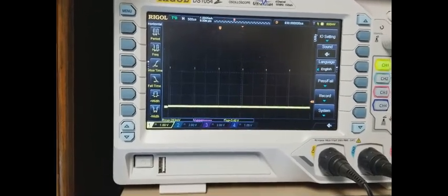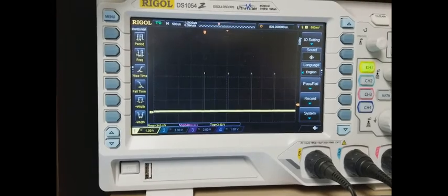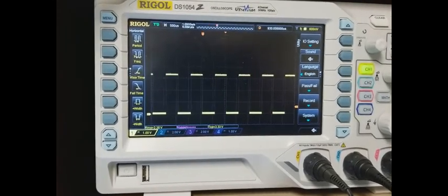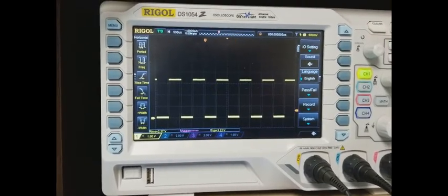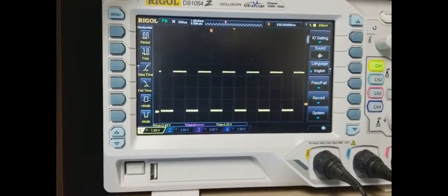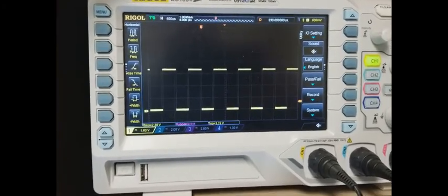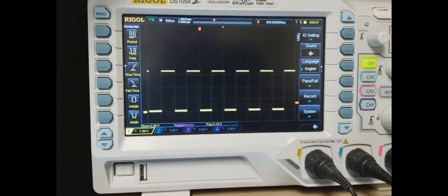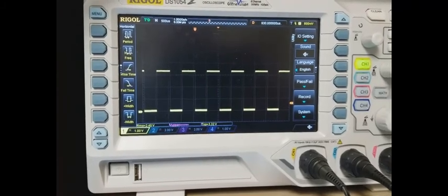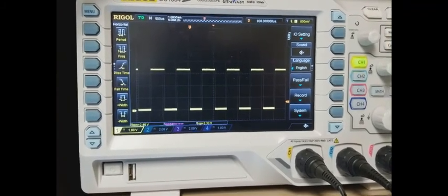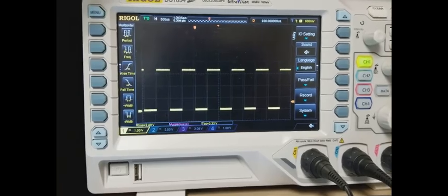Looks like we get a little residual spikes in there, but that's not going to matter, because keep in mind that what we're trying to adjust here is the dim setting, so that when we go from bright to dim on our displays, we've adjusted and balanced the light output on the UHF 7-segment displays to match any of the other indicators in our cockpit.